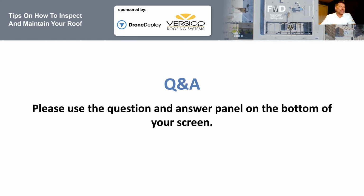And then the last one about TPO is power washing. Absolutely, there's power washing. People use floor scrubbers. It's funny that with the whole reflectivity thing that really happened over the last decade or so, we've actually seen an industry almost start that cleans roofs. Who would have ever thought you'd be up power washing and cleaning your roof so that you can regain that initial reflective quality that those membranes provided up front. Once they get airborne dust and dirt and other construction things, it's nice to keep it clean. And some owners are very good about keeping it clean, and it does help keep their cooling bills down a little bit.